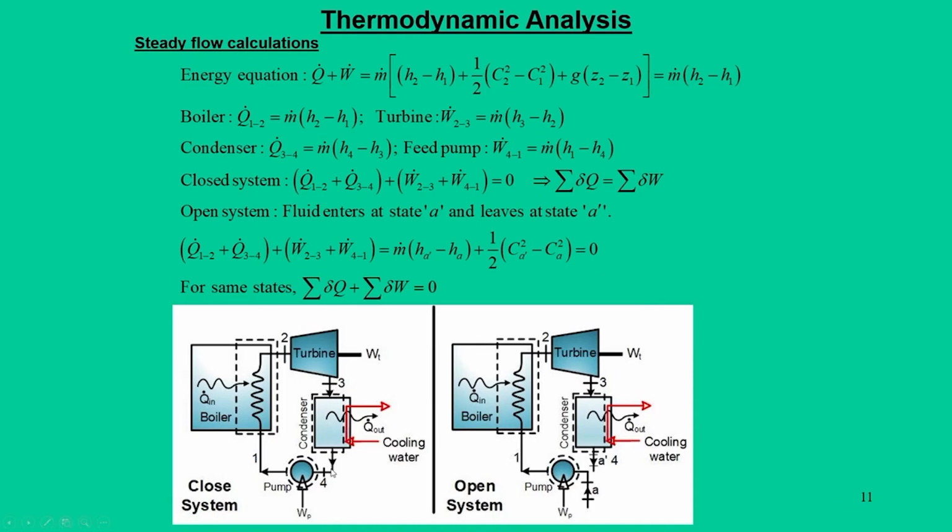So, we can see here that the working fluid enters the system at state 1 in the liquid state, that means through the pump it is a liquid. When heat is added it changes its phase, so it becomes steam. It enters the turbine, and then when it enters the condenser, it releases its heat and gets condensed, again coming back as a water medium. So, it enters and leaves in the same state, that is, the liquid state.